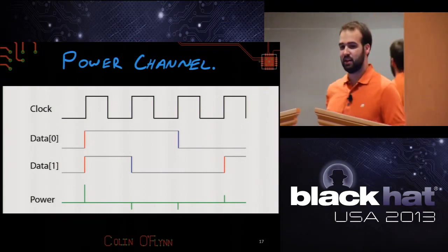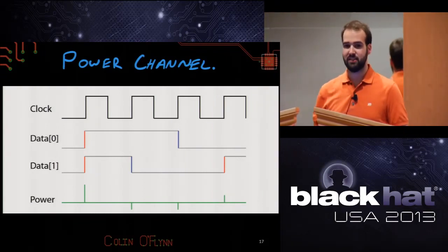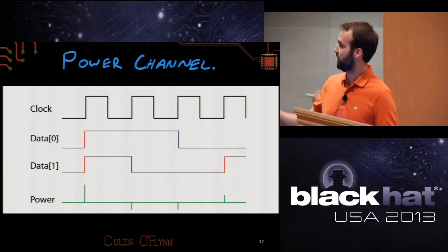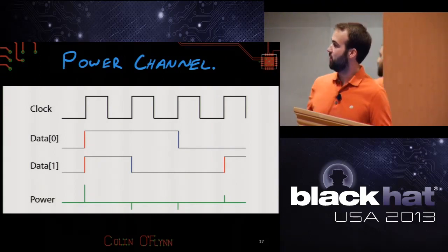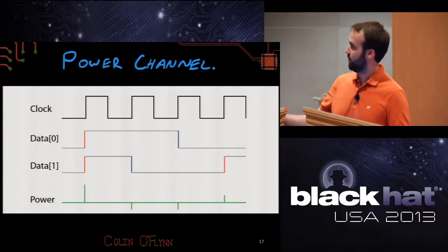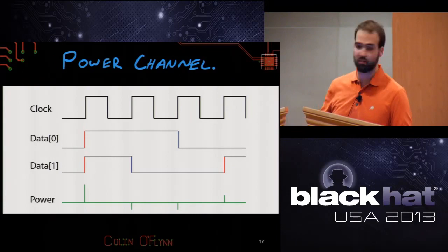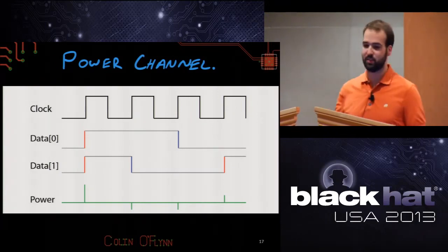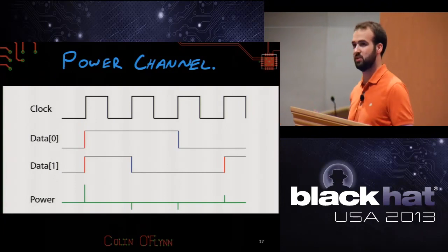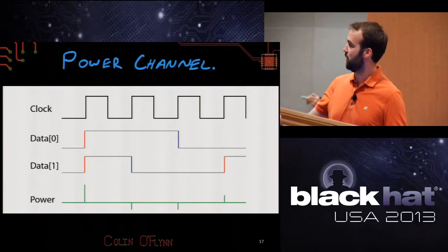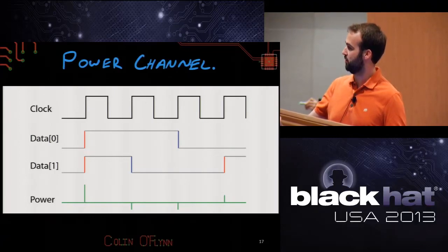Importantly, all of those data lines are switching at the same instant in time. They're switching relative to a clock. So we have a clock on the digital system, and you have the 2 data lines. When that first clock edge happens here, these 2 data lines switch. So this side, first clock edge, 2 data lines switch, and there's a big positive spike, because 2 of the data lines are switching. At the next positive clock edge, only one of the data lines is switching, and it's going from positive to negative, so we see a bit of a negative spike.